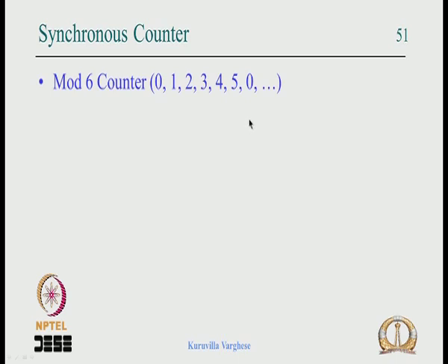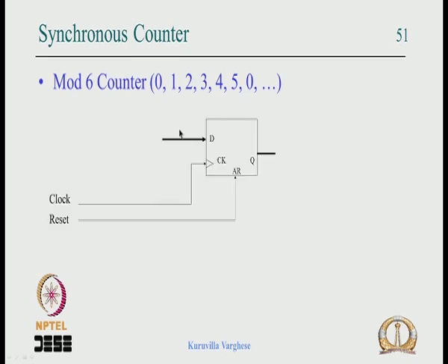We use binary encoding, so that means we will encode the 6 states in flip flops. So we need log to the base 2 of 6 number of flip flops, which comes to 2 point some number, so we have to use 3 flip flops. So let me put 3 flip flops. Now I am already abstracting. In your basic course you would have already put 3 separate flip flops and tried to design.